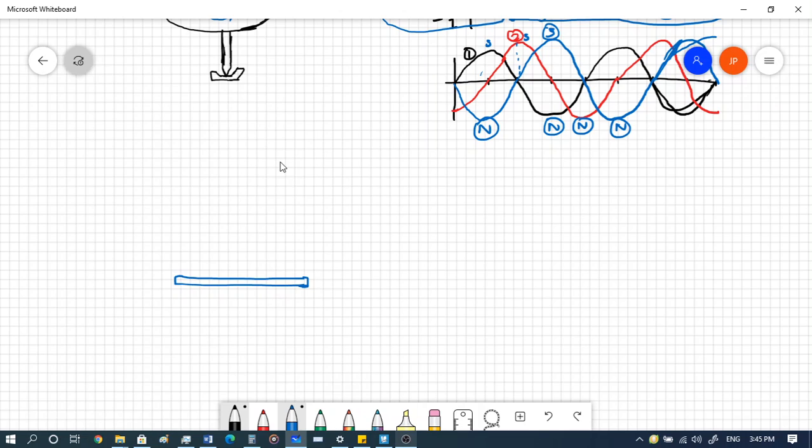If you look at this disk from the front, it looks like a single long bar, because you won't see a disk when you look at it from the front view, right? And what we have is a magnet, an electromagnet, which is basically the pressure coil. So the magnet corresponding to the pressure coil.